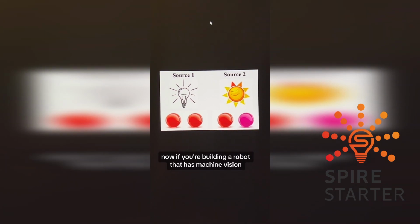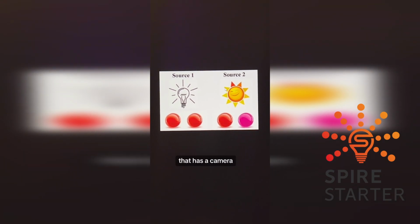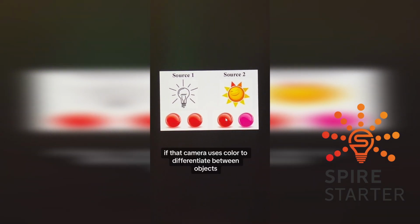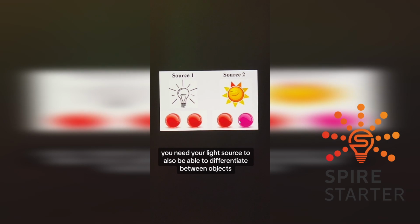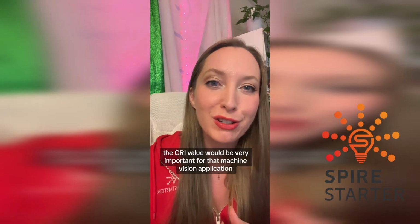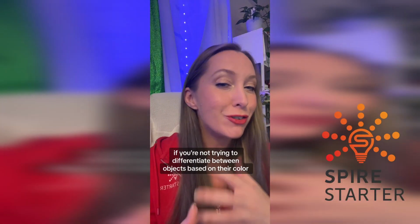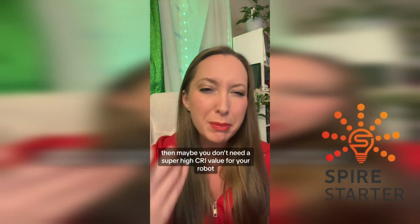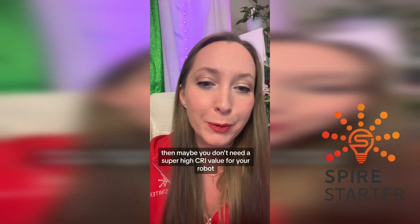Now, if you're building a robot that has machine vision, that has a camera where the camera is helping it do things, if that camera uses color to differentiate between objects, you need your light source to also be able to differentiate between objects, between the different colors of those objects. So in that case, CRI value would be very important for that machine vision application, but maybe not for all. If you're not trying to differentiate between objects based on their color, then maybe you don't need a super high CRI value for your robot.